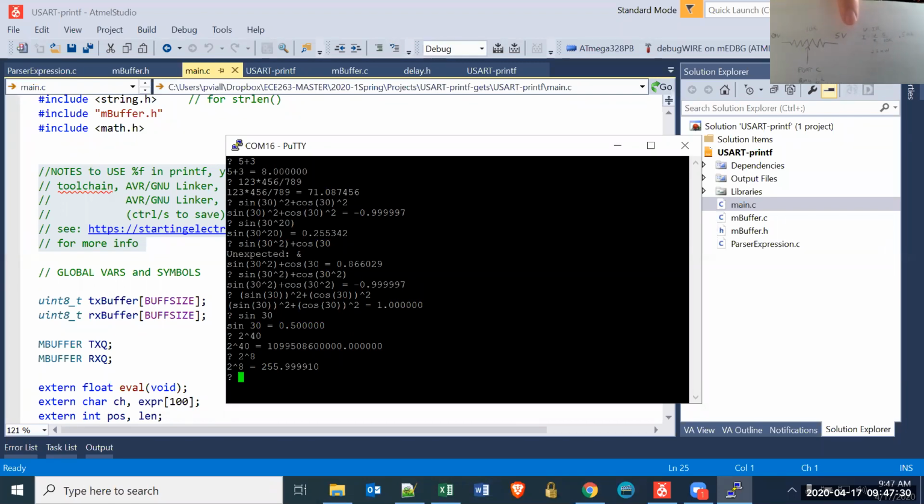Now, I know some of you haven't seen Ohm's law yet. Let me make my screen a little bigger. Okay, yeah. There's a thing called Ohm's law, V is equal to IR. When you get to circuits, you'll see that a lot. Or current I is equal to V over R, or 5 over 10K, or 0.5 milliamps. So 0.5 milliamps, that's 0.0005 amps, is always flowing through this resistor.